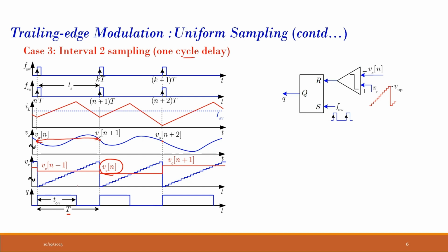So the more you delay doing things, the more difficult it becomes, right? In life also, if a task is delayed, it becomes harder and more difficult to do. Similarly, in this control system, as you increase the delay, it will reduce the effective phase margin. And when the phase margin is reduced, your stability becomes poor.